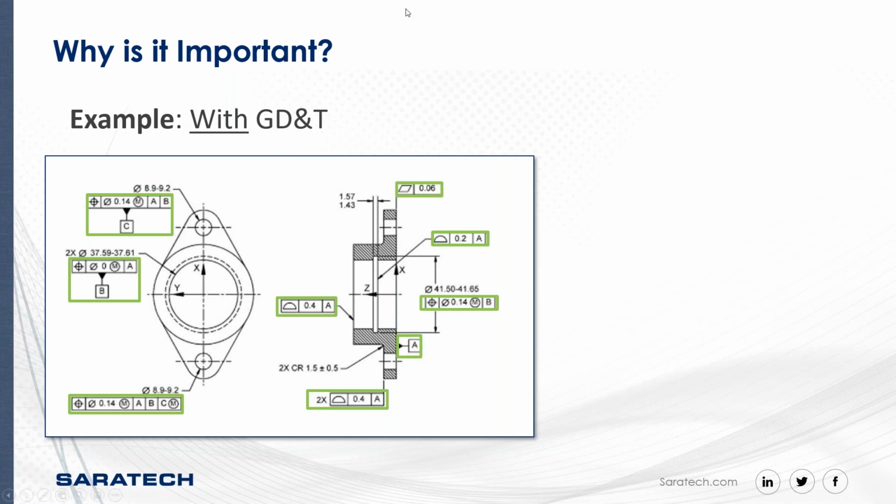But what I was going over on this slide was basically what the different GD&T features and feature control frames are defining on this part. So I apologize if I'm repeating myself, but this here is defining the flatness tolerance of this surface here. So this is a form tolerance. This here is the surface profile tolerance, defining this top surface, this one here, and this one here relative to datum A. So this is a feature-to-feature relationship that's happening to your primary datum A.